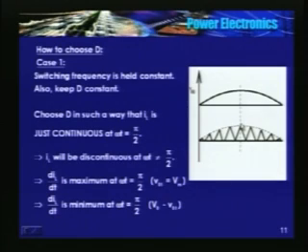It has a maximum value, decays very slowly, and I am telling that current is just continuous at this point. So what will happen here? A very small current decays much faster. So therefore if the current is continuous at this point, there will be durations of zero current in the remaining period. Okay, durations of zero current in the remaining period.